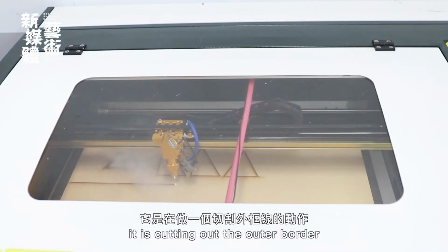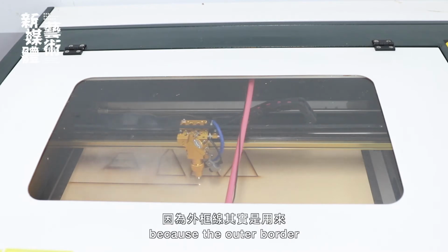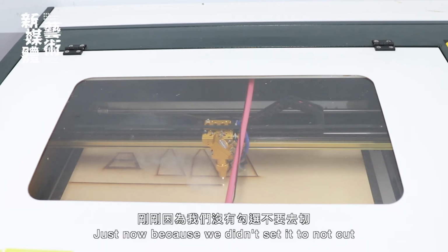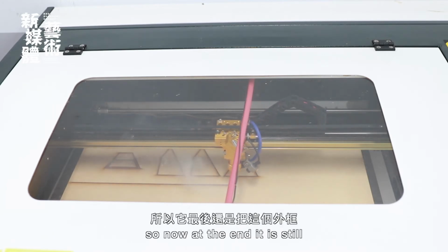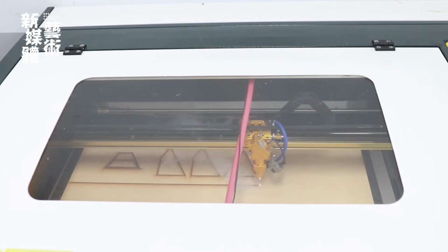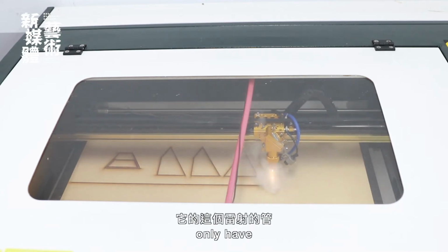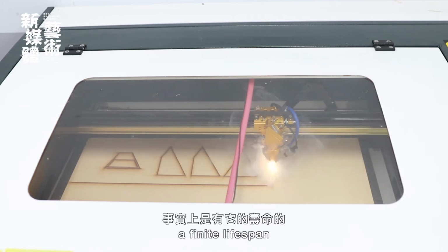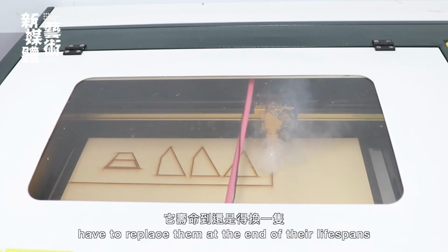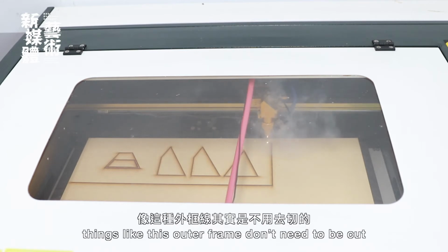Now, it is cutting out the outer border. We can change the settings so this outer border won't be cut, because the outer border is just used for positioning. Just now, because we didn't set it to not cut, at the end it is still cutting out the outer border. Basically, laser cutter tubes only have a finite lifespan. So really, if you regularly use it, then you will eventually have to replace them at the end of their lifespans. So sometimes things like this outer frame don't need to be cut.